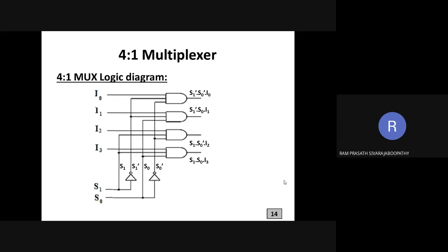But notice one thing. The number of inputs for the AND gate is 3. Okay. What about the OR gate? Number of inputs for the OR gate? How many OR gates do we need? 3 inputs or 4? Respond. Kindly check it. We are having 4 things to be ORed. Yes, very good, Srigari. 4 inputs must be there for our OR gate. So the final expression will be like this.